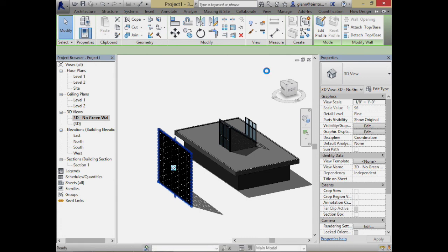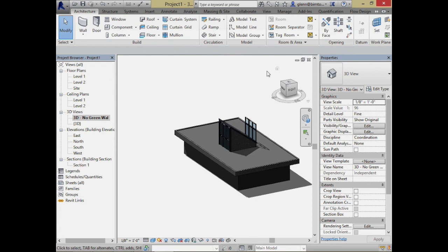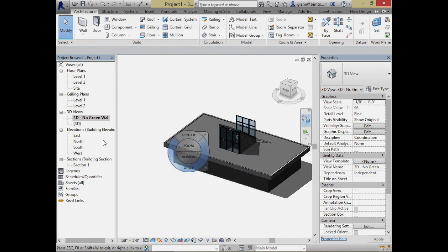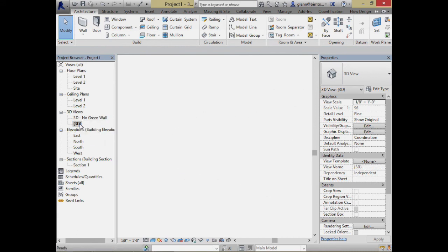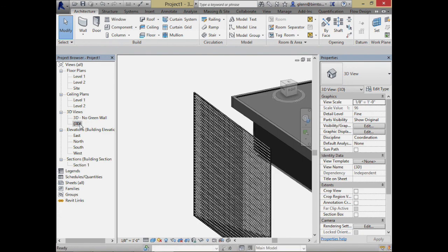Just sort of understand whether you want to show it or you don't show it. Because once you've figured out that it's there, we can put a reasonable approximation there without the detail and really speed up your graphics operations, so that when I need to do a lot of mass movement, I'll be in this one. When I really want to see what it looks like, I'll come back to this one. So don't be afraid to turn off things just to speed up, because especially with things like this, when people do these very articulated building facades, it gets to be very resource heavy.